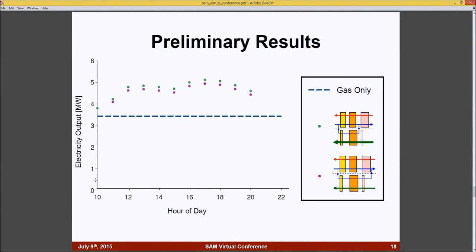My personal hypothesis for this deviation is that the empirical model, which is based on a real facility, probably didn't explore cases where the entering solar field temperature was very high and the exiting solar field temperature was also very high, because it was built for a traditional concentrating solar thermal facility, which wouldn't run in that regime. But if anyone has any other insight or explanation as to what might cause this deviation between the models, I'd be really interested to hear it in your feedback.